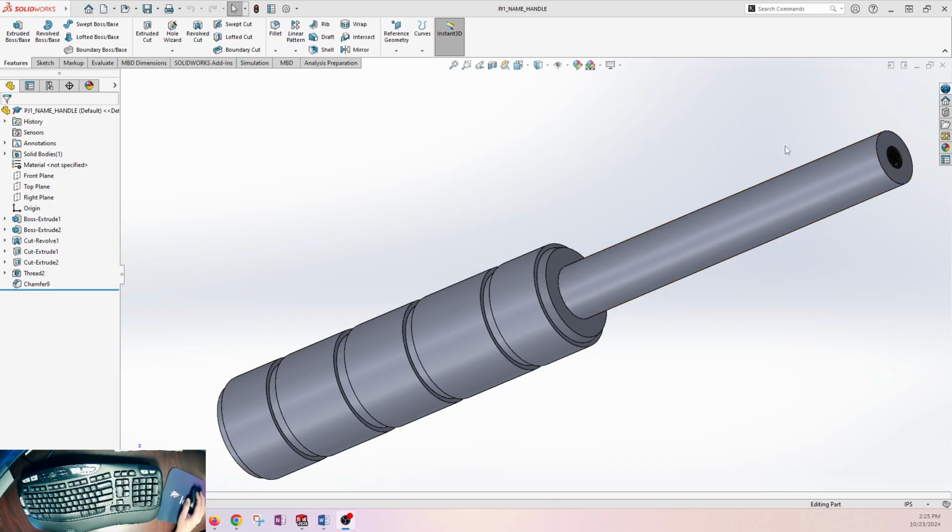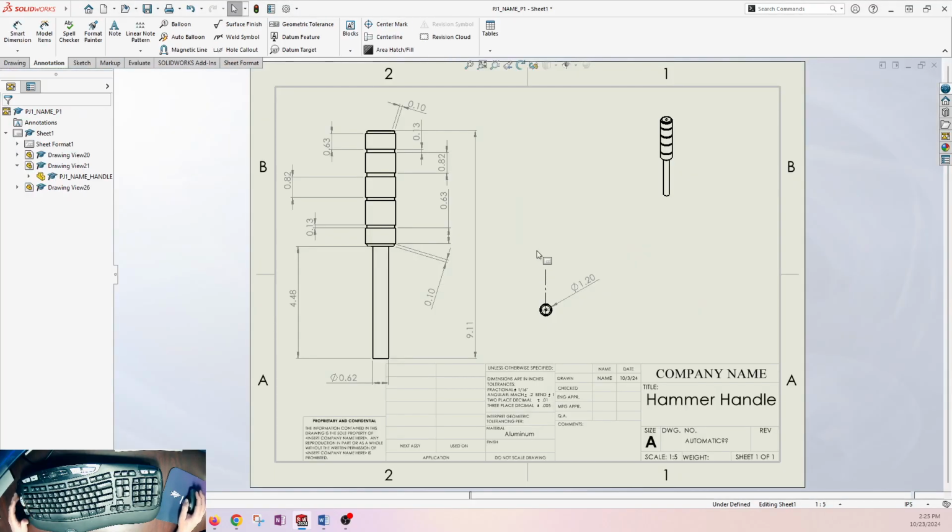So I'm going to go through our drawings. Let's start. I'm sorry, I may be jumping around a little bit because there's a lot. Okay, so if I look at this, first thing I see, it's not an ANSI standard. The title block is not cleaned up. There's lowercase letters. I went ahead and retyped some things like company name and automatic here because nothing was coming in automatically. Somebody had gone in here and typed all of their information in, which we know we're not supposed to do.